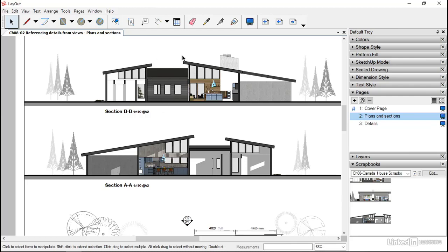However, what tends to happen is it gets a bit messy, and when you're trying to read these drawings, maybe this is printed out or reduced on a photocopier or something, then you might find that it's not very clear. So always a much better way is to highlight the whole thing. So this is detail 1 and detail 2, and then on another drawing have this then set at a scale of maybe 1 to 50 or 1 to 20 or the imperial equivalent, and then on that one highlight the areas where you're going to take the details from. So you're basically scaling up to levels of detail that makes life a lot easier for people to understand.